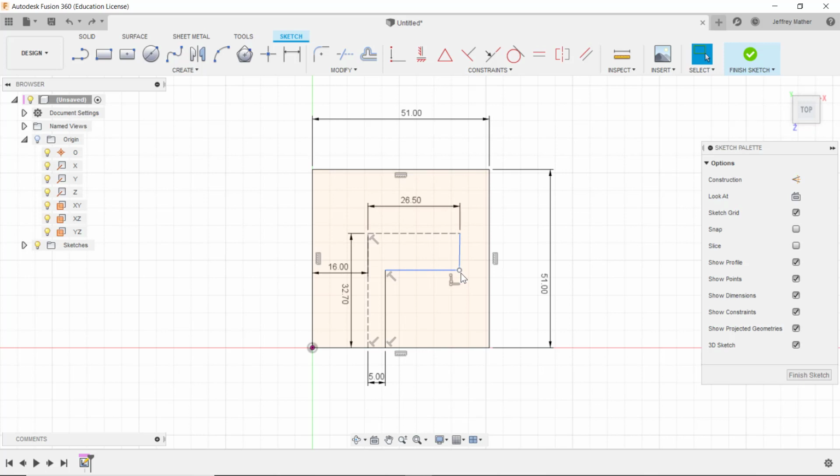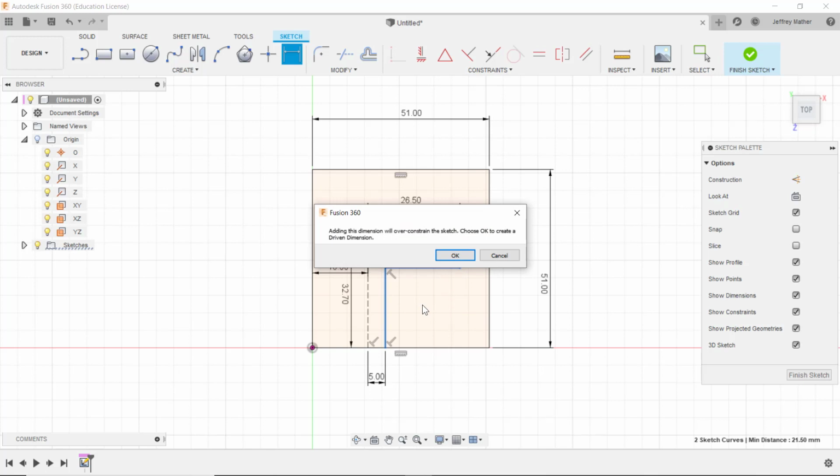And so if I drag these points, we see that this line isn't staying vertical. And so I'll do a vertical or horizontal constraint, and I'll select on that line, and now that line is going to stay vertical. I could select this one, but it's already perpendicular, so that one's okay. Alright, and then let's try to put that dimension in again. And so I'll dimension from here over to here, and you have that dimension as 21.5.